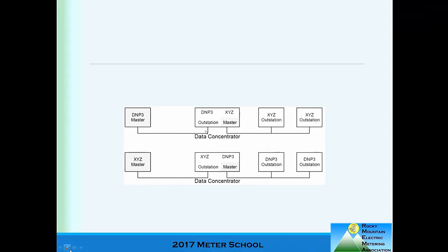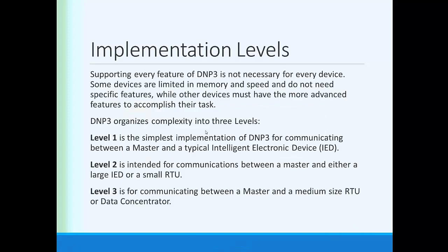But all of the devices, all the RTUs, all the meters, all the IEDs in the substation are now, for intercompatibility's sake, operating with DNP. So you need some type of communications converter to convert the database from communications in one protocol to communications in another protocol to bring the same database, the same content from one area to another. This is a place where the Orion can be very helpful.